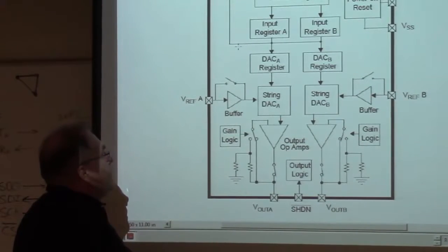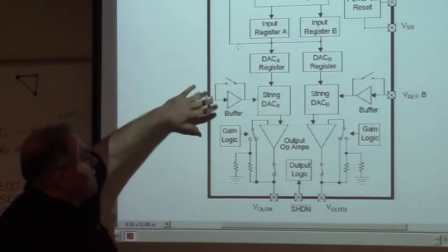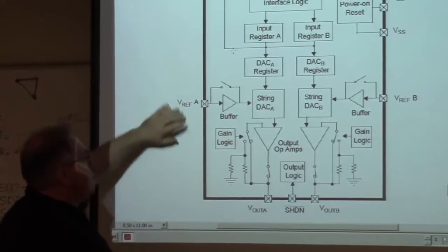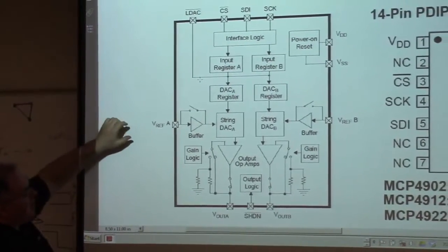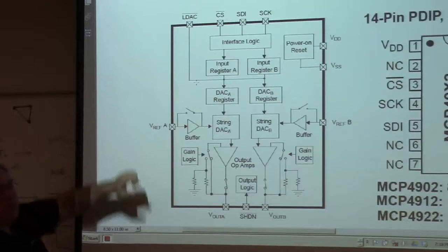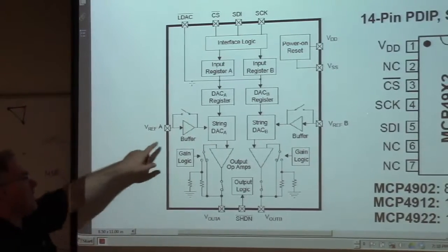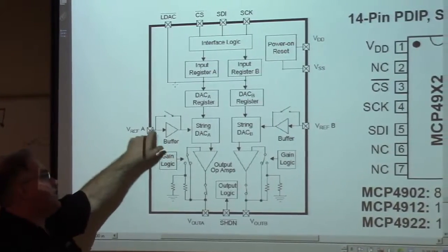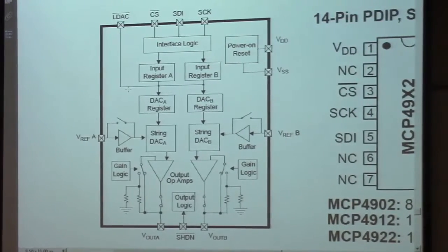And sometimes, we could probably use it either way because we have a really strong 3.3 volts that we're using. But sometimes when they use a reference for a DAC, they use really specialized reference voltage chips, and they have very low output current, and so they have these nice internal buffers that you could use to minimize the load on your reference voltage.